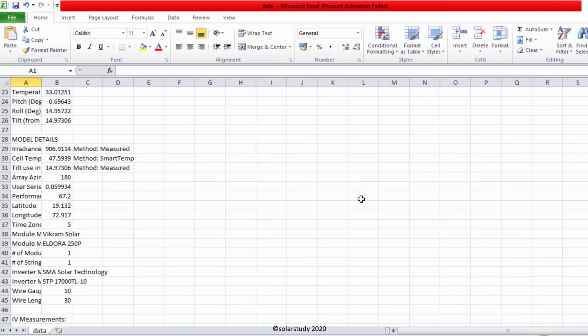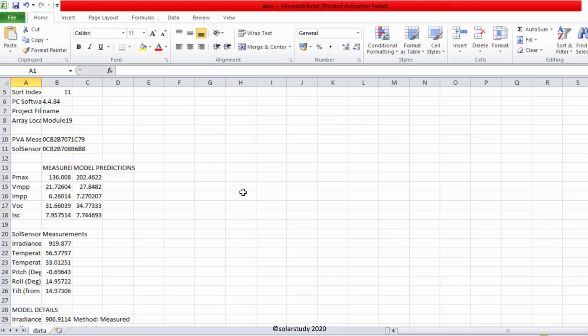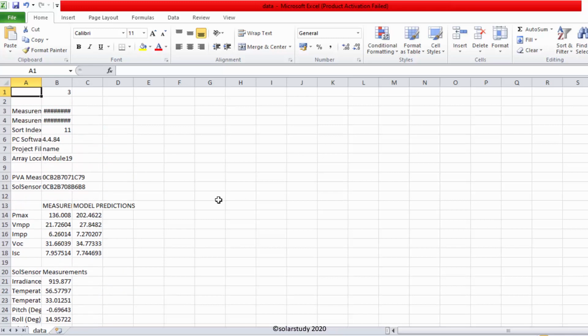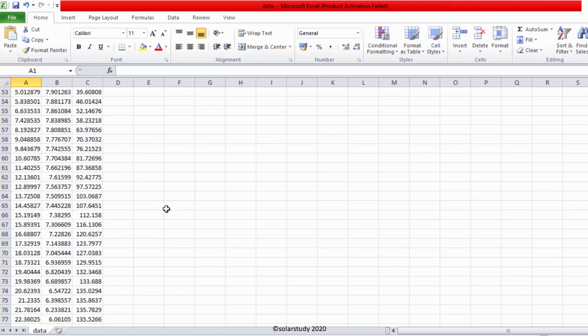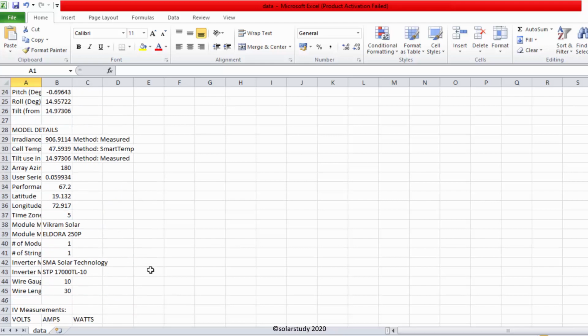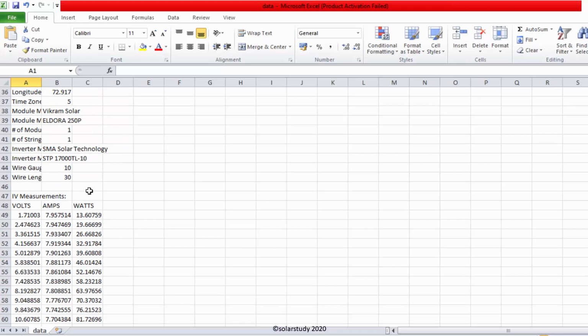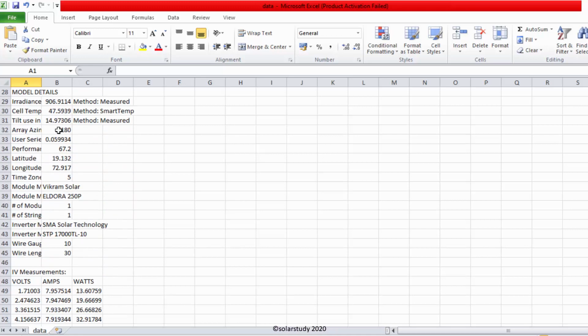Let's see one of the SCADA data which I got for the field measurement data here, like after installing. I can go for the previous data also, test 1 and test 2, because I already made the program for this one. So I'm just explaining the field data here. They measured the voltage and current after installing the panel in the field. Again, whatever they measured in the flash test is the same as presented here during the field measurement data.